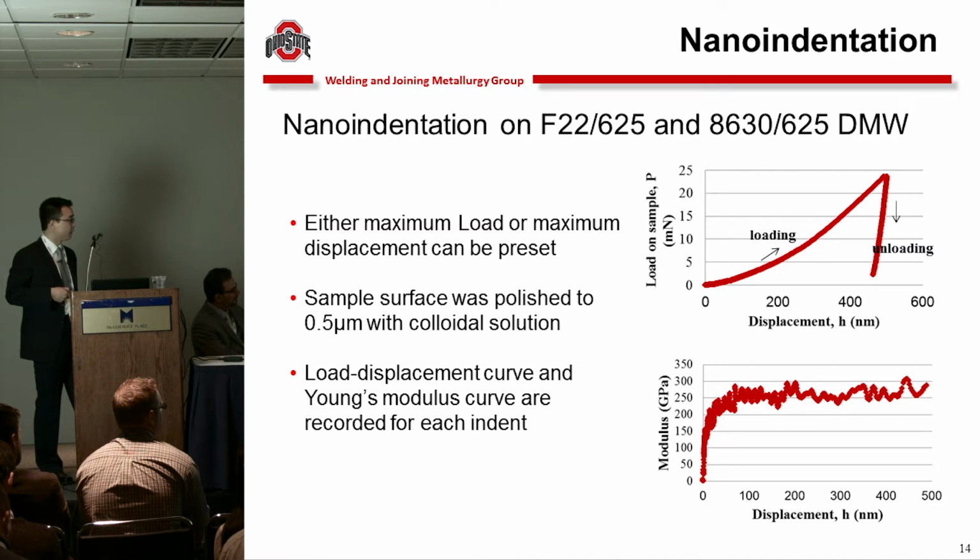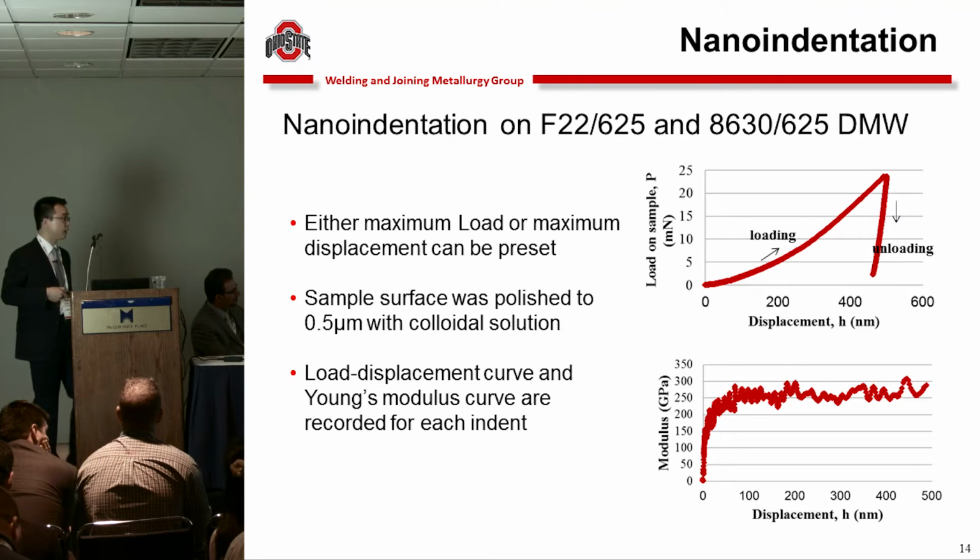And this is a load displacement curve. This has 2 stages, loading stage and unloading stage. The unloading curve goes back a little bit because of the recovery of the elastic deformation. And this is a record of the Young's modulus with displacement at each indent.